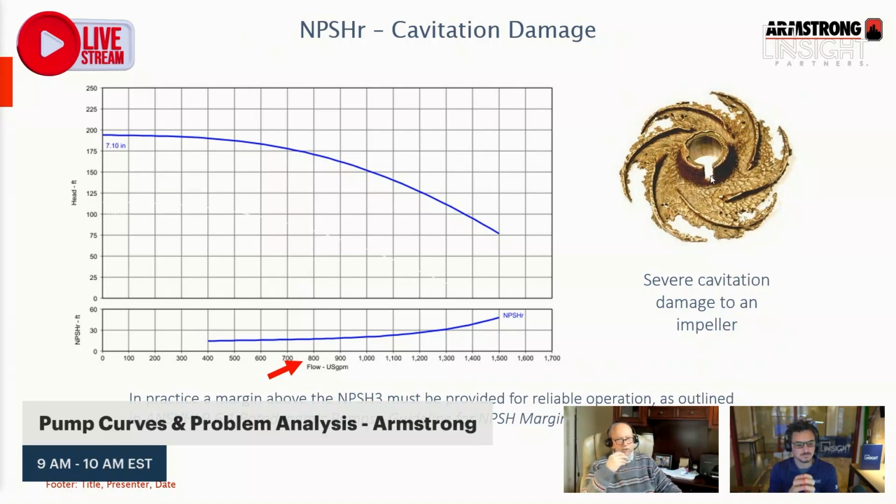But because the engineer designed it to maintain the level all the time at the top, as they dropped the level in the tank, the NPSHA constantly moved up and down. They took less than 3 months to do damage that looked like that to the impellers, and they did it on 2 pumps that were, I want to say, 100 horsepower apiece.